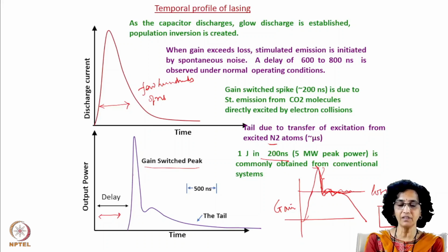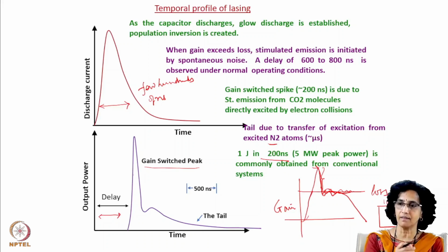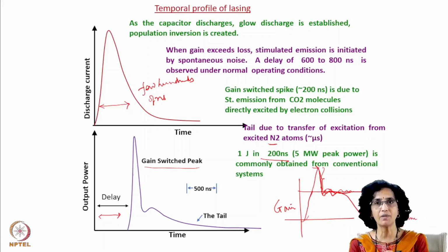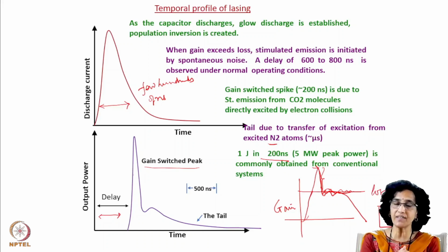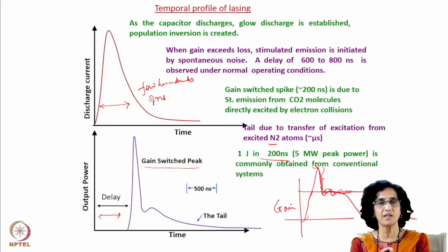So today what we have learned is we have tried to understand the pulser for a laser. The pulser consists of an energy storage capacitor which is charged through a resistance from a high voltage DC power supply, and it is switched through a spark gap, right? And because the voltage is very high, kilovolts, the peak currents are also very high, and therefore this spark gap is able to take care of this high voltage, high current, and we are also able to get a very short discharge,